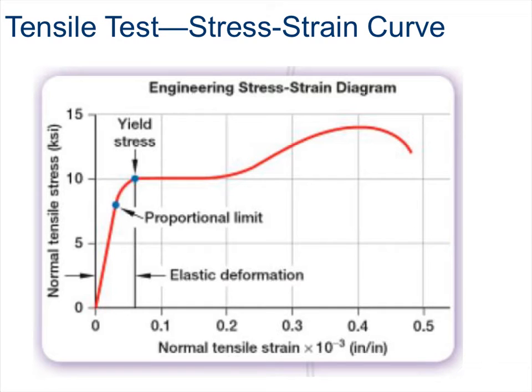The idea is very similar to the behavior that a rubber band exhibits when stretched. Regardless of the time over which the load occurs, if the load is removed from the material while it's in this range of elastic deformation, the material will return to its original dimensions. Virtually all mechanical and structural designs that must withstand temporary loads are designed to take advantage of this mechanical property.